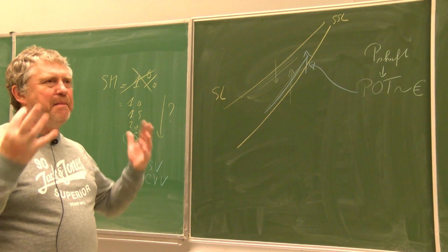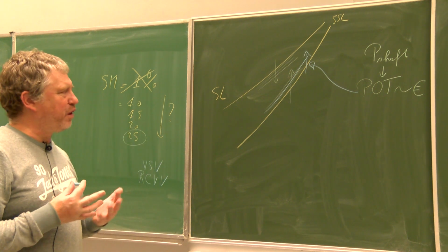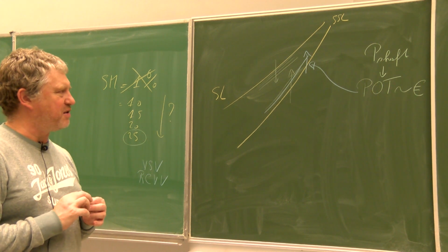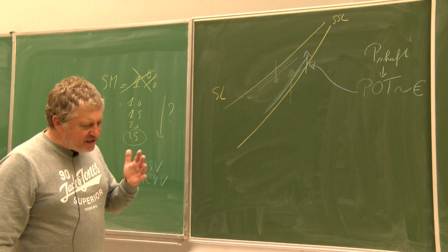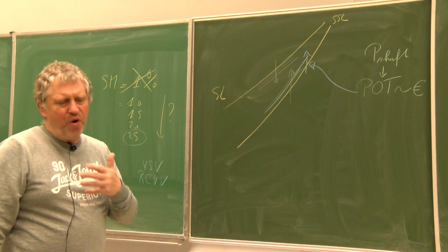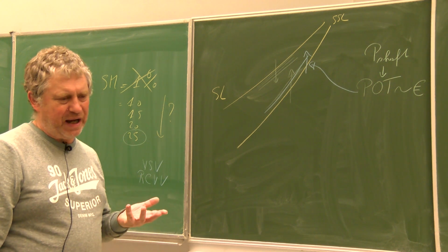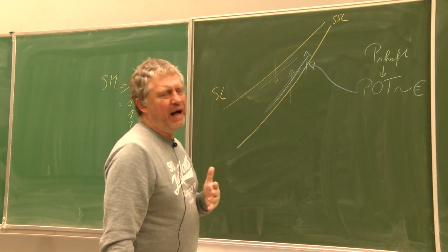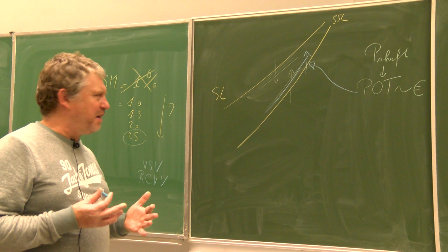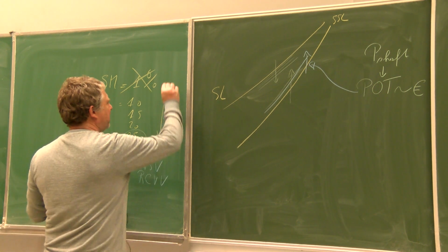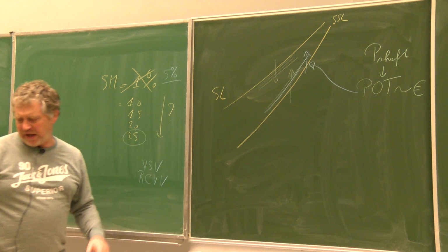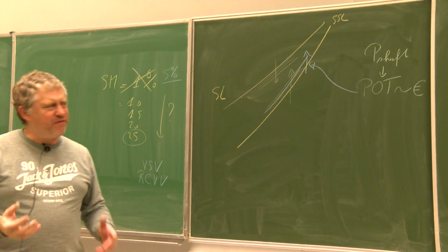These are degradations at the level of maintenance and accuracy of some elements. You can also have a Reynolds number effect at very high altitude that makes the surge line go down. But all this together, maybe you will reach something like 5% altogether.